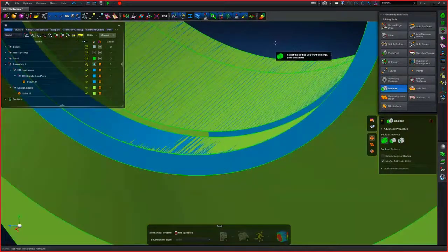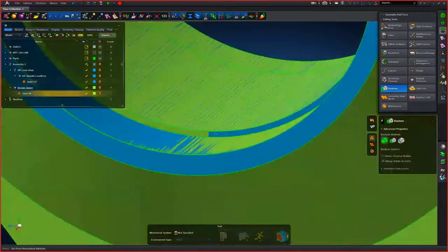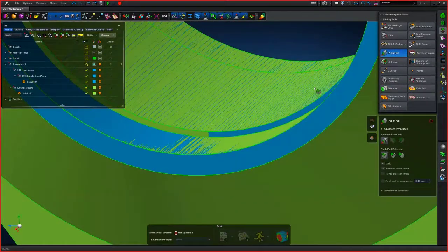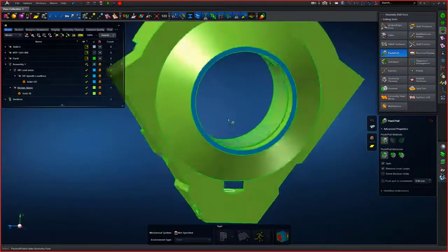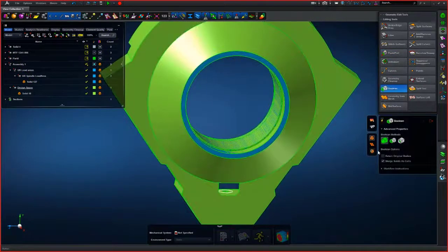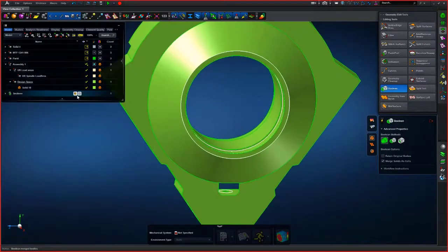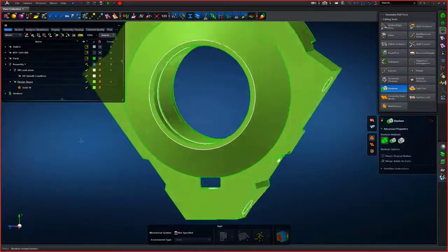What I've picked up is that the rendering indicates that this area, and it's a bit difficult with this thing highlighting, but there's an area on this ridge where the shading doesn't blend. And that's a giveaway that those two surfaces aren't properly aligned. So the CAD operation wasn't perfect. I'm just going to bring those two together and then try my Boolean operation between these two bodies again. And there we have it. Now there's only a single body.